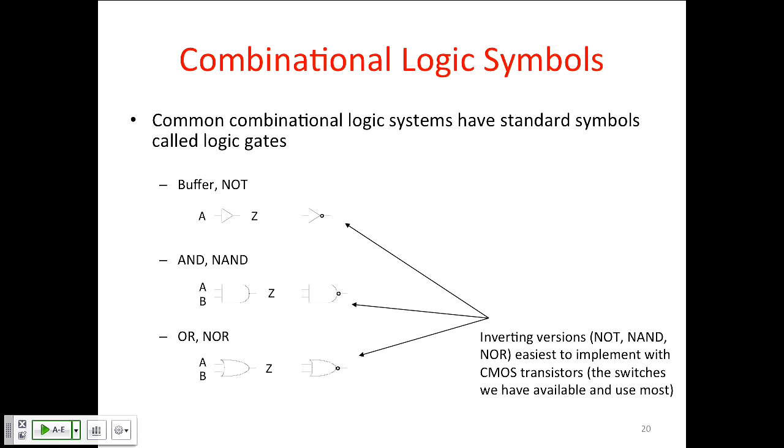And the nice thing about this technology is that each stage kind of buffers the signal electrically, because at each stage, the inputs are connecting the output to the power supply. And so you kind of get to start over again being driven directly from the power supply. And so it's easy to chain these logic gates together to build very deep circuits that all function correctly, right? And actually, in this technology, if somebody gives you a design of an AND gate, what it will be is actually a NAND followed by an inverter. That's the best way of making an AND gate in this technology. Okay?